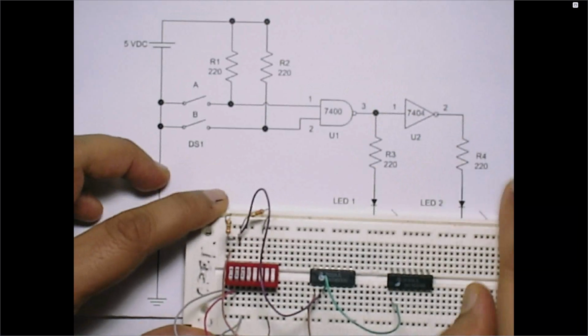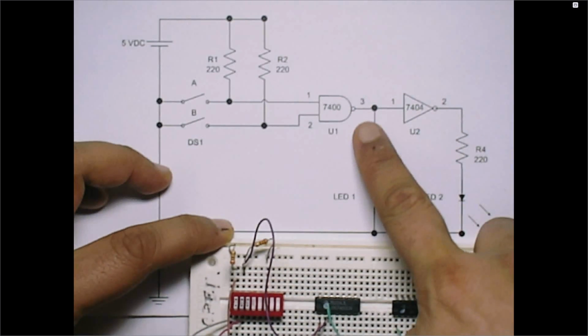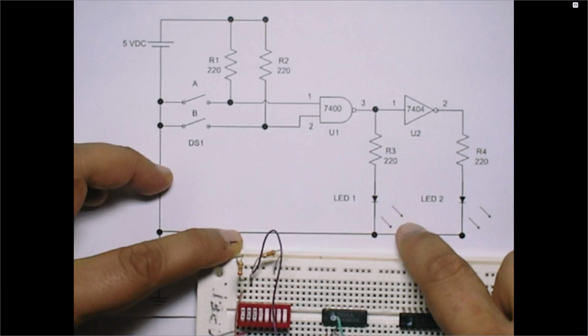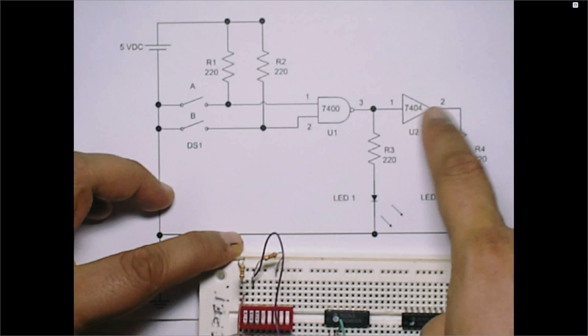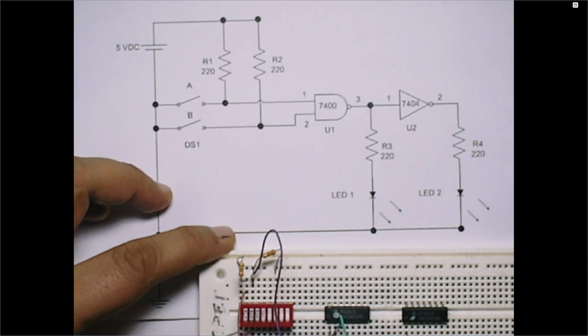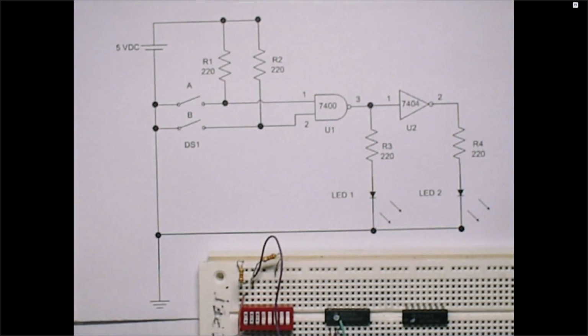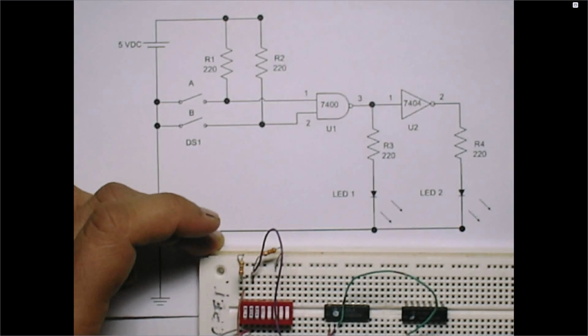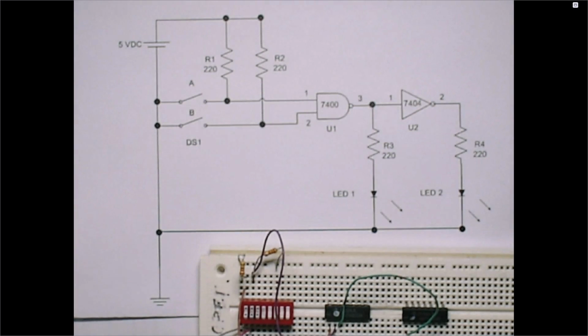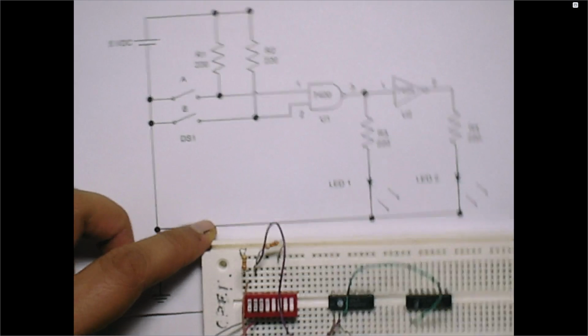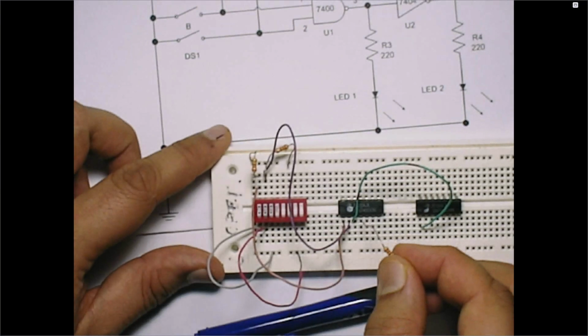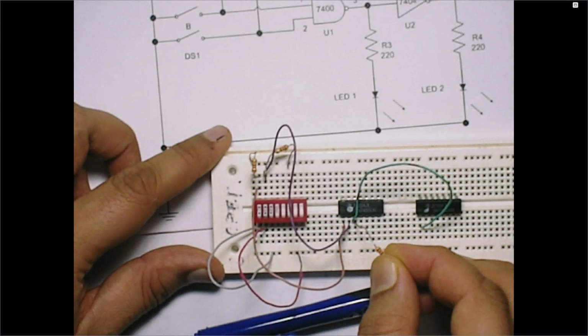And now I'm almost done. What I need is to connect a resistor to an LED to ground, just to show the output for this point, for pin 3, and for pin 2 I do the same. Now to do that, let's say from pin 2 I actually need to run a resistor, right? I can probably use a resistor directly. Again, this is a 220 ohm resistor. Remember the color bands from the EETC circuit class. I'm not explaining the color bands again here. So this is my pin 3, from the same pin. You can use the same column again because you have many other points not used yet.